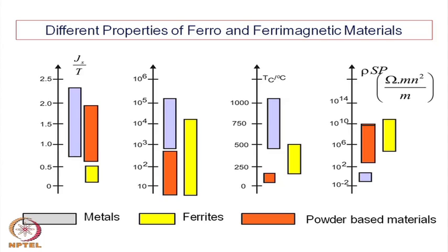because, as you have seen earlier in our discussion of semiconductivity of oxides, it is the oxygen partial pressure which controls the charge carrier concentration, whether it is electron concentration or hole concentration, and that in turn determines the electrical conductivity.